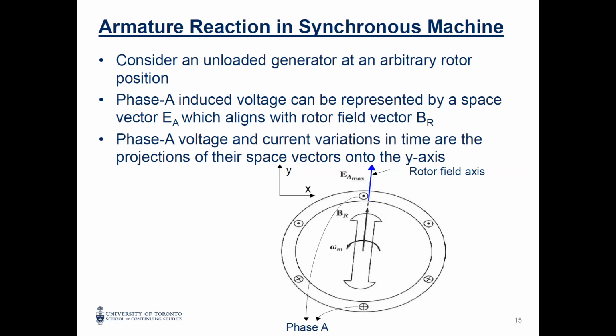So let's go step by step to understand why the armature reaction in the synchronous machines is important. We assume that we have this machine. As we said, the field will be at the rotor. The phases A, B, and C, for example, here phase A, are at the stator. This is normal for the synchronous machines.